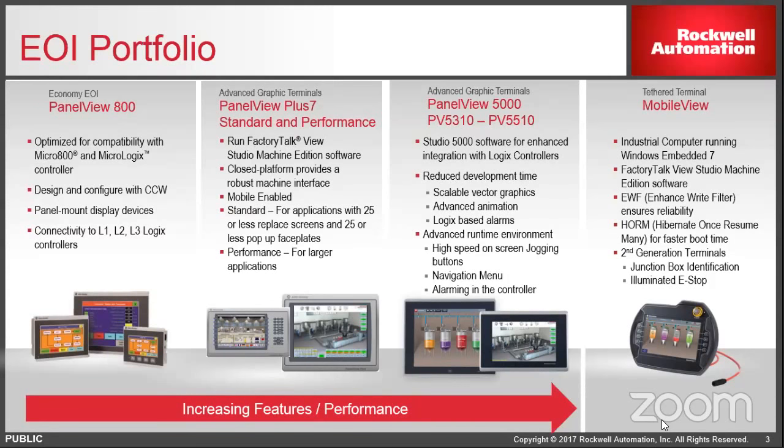And so just starting off, what we call the component class HMI is the PanelView 800. This is the class of HMI that we use a lot for MicroLogix, CompactLogix L1, L2, and L3 connectivity. And this is programmed in our Connected Components Workbench software. So it's a free software package. It's the same software package to do a lot of things, including your controller programming for the MicroLogix. So I'm not going to talk a ton about that, but if you have any other questions on that, we can talk a little bit later.